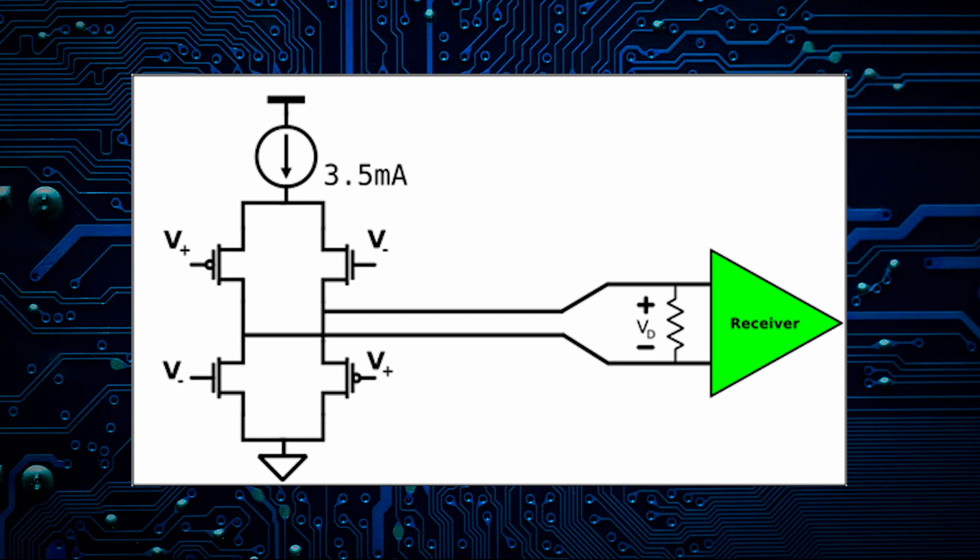Why is this system used? What benefits could we obtain from doing this? Well, the trick is that the difference in these signals does not occur precisely in the absolute state values, like 3 volts or 0 volts, but occurs in specific calibrated values, such as 200 millivolts. What this causes is noise immunity, because no matter how much the signal deforms, this difference will continue to occur and we will be able to maintain excellent communication integrity. For this reason, high-speed communication systems use this method.